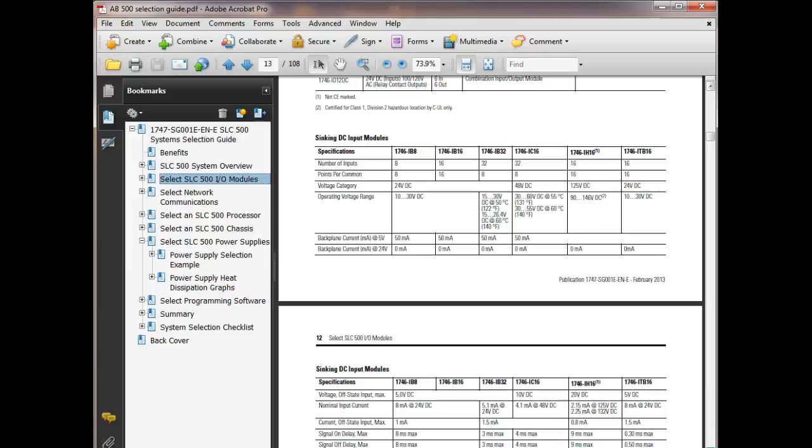And I wish we had time to do communications. The book does a pretty good job on what we call the data highway, which is a method of communication. But it talks about Ethernet and it talks a little about that. So, odds are you get into a real big plant, they're gonna have all these hooked to each other. And that way you can go in there and you can select a node. When you say who's active, right now the only one that says it's active is this PLC. But when you look at who's active, it'll show you the station. It'll show you all the stations out there. And you can go to an individual station, pick a station, download the program off that, play around with it, go to the next station. And all these guys can communicate with each other, which is pretty neat. We'd have time to do that, guys, but